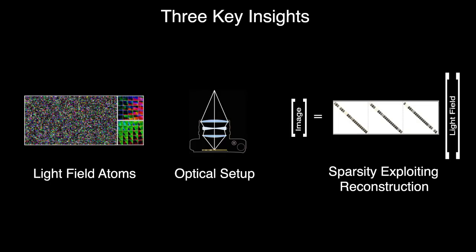We give 3 key insights into both optical and computational camera design parameters. First, the fundamental building blocks of natural light fields, light field atoms, can be captured in dictionaries that represent such high-dimensional signals more sparsely than previous representations. Second, this sparsity is directly exploited by nonlinear sparse coding techniques that allow high-resolution light fields to be reconstructed from a single coded projection. Third, the optical system can be optimized by preserving the information content of the light field atoms.